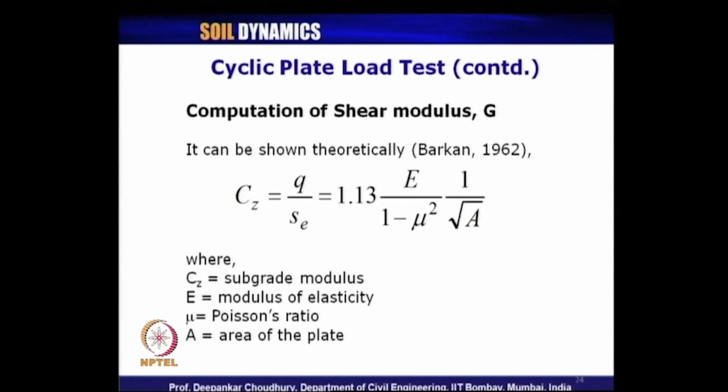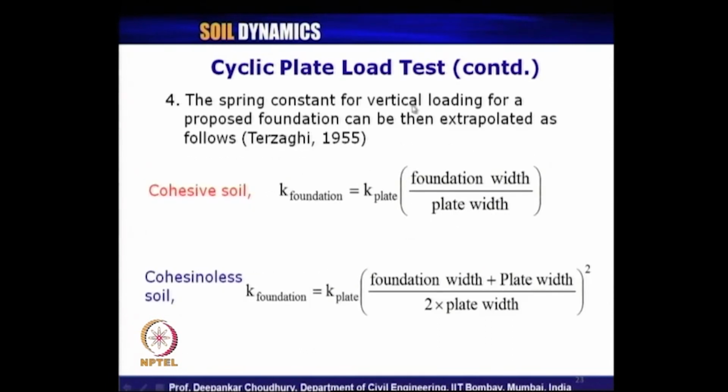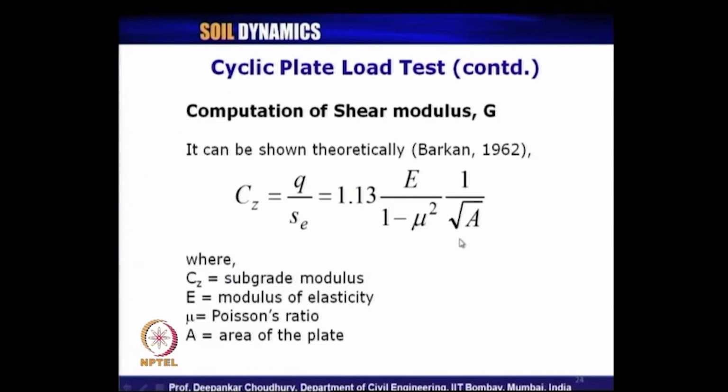For other modes of vibration, that is horizontal, rocking, pitching, etc., we will see other expressions available to correlate the dynamic shear modulus with Young's modulus. As mentioned in the previous slide also, this is valid only for vertical loading.